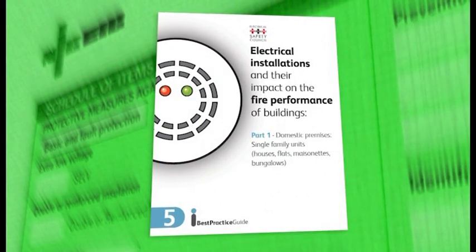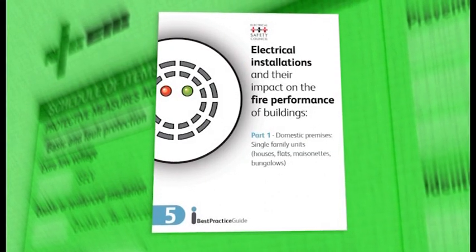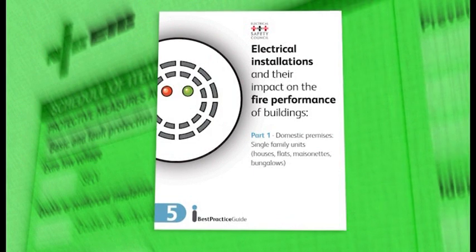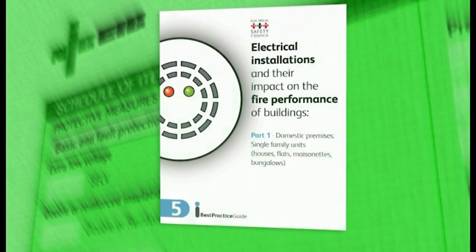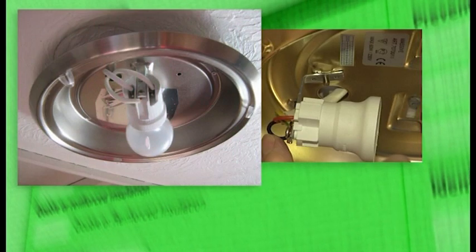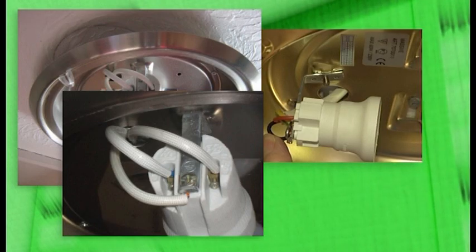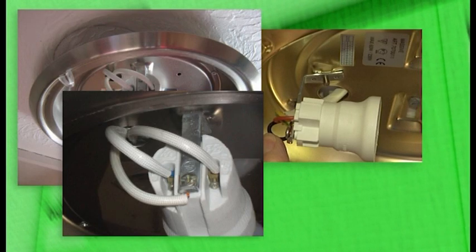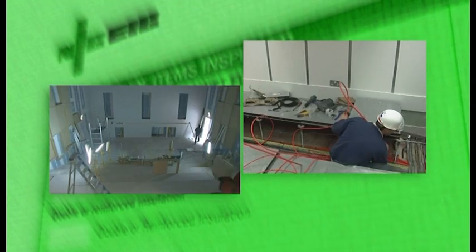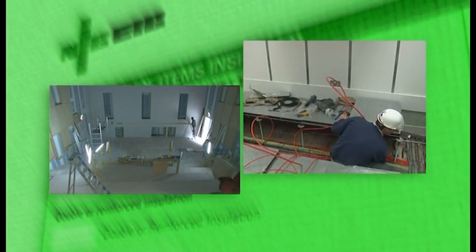It's worth mentioning here that there's a new best practice guide from the Electrical Safety Council, which examines electrical installations and their impact on the fire performance of buildings. With regards to thermal effects, a typical example to check for is that the heat-resistant sheathing, provided with some types of light fitting, has been fitted to the cables entering the luminaire, so protecting the supply cable from the heat of the lamp. The check for fire barriers and sealing would be an ongoing check during building construction.